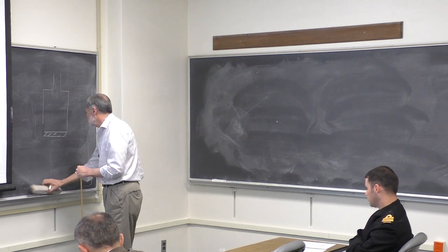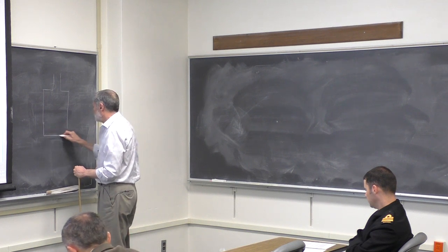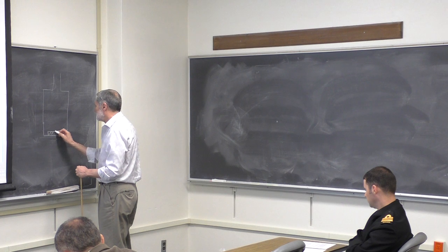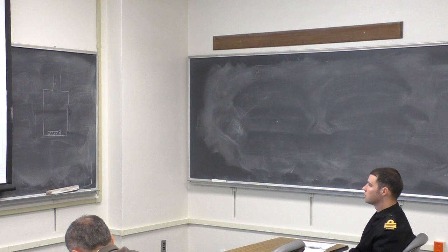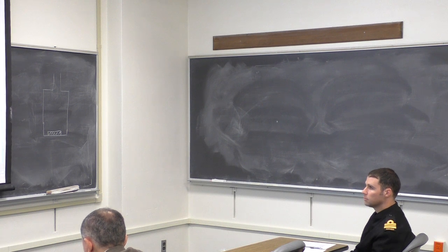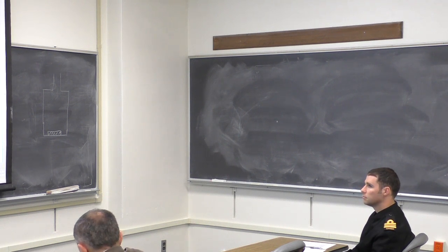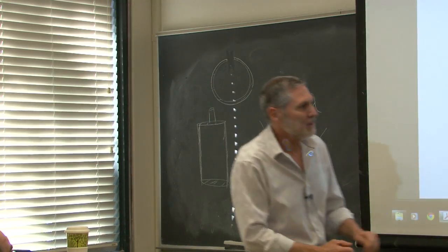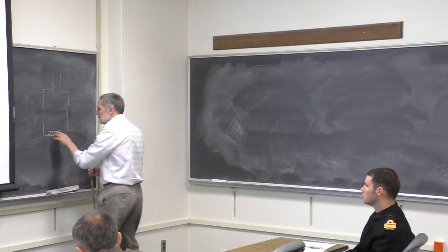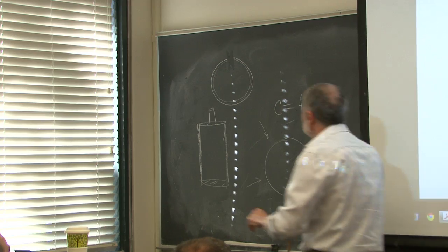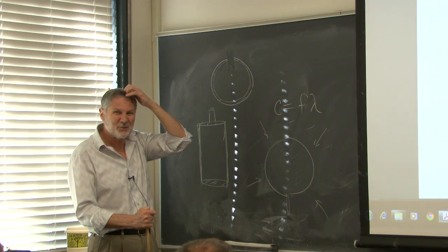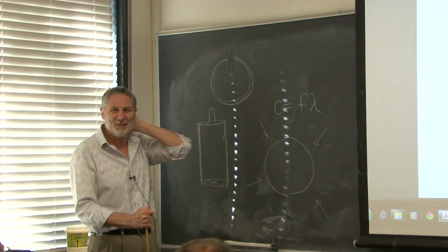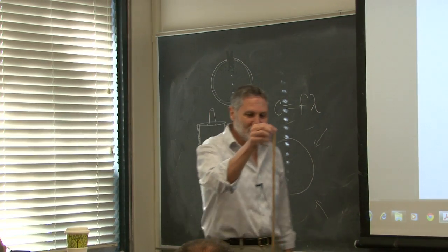Okay, how about this? I don't think this is going to be practical, but you can imagine something like this, where that's the piezo. After a few times going through this, what hit me was something that I know well about, and this may surprise you: you may not want to drive this at the resonant frequency. You may want to drive this at twice the resonant frequency. Does anybody know why? Okay, look at this. This is a pendulum, right?